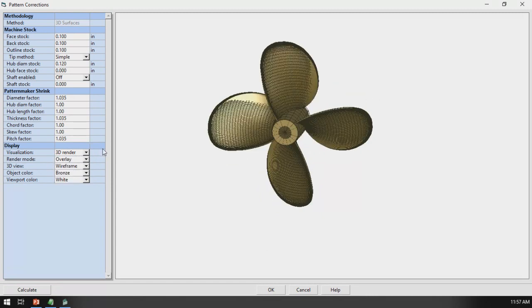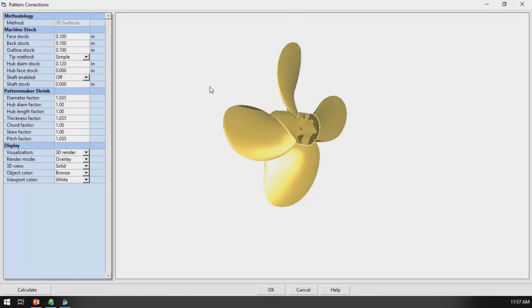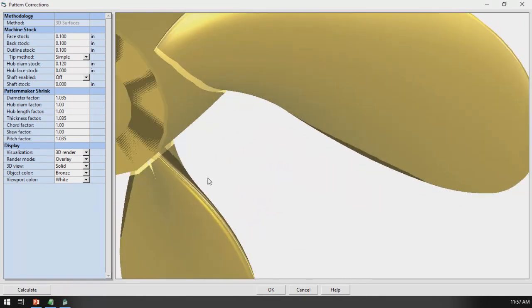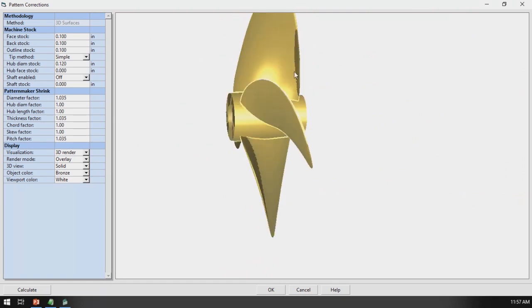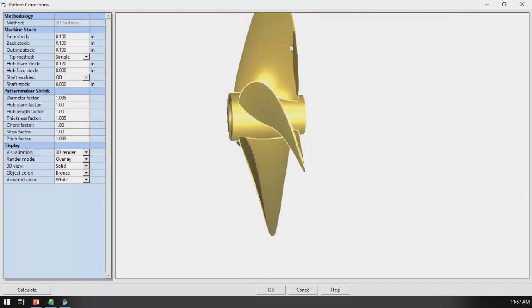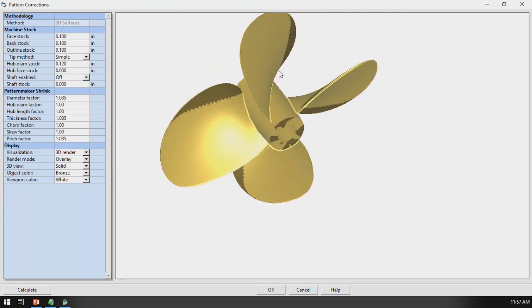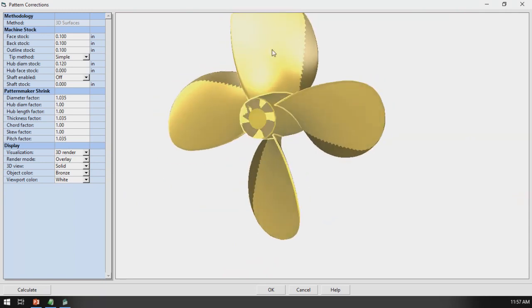All right. Hopefully that answers any questions about this pattern making utility and making compensation. This is just another way to visualize the same thing. Again, offset surfaces instead of a wireframe, it's yellow. But what this allows you to see is where your original design penetrates your pattern. And that's an indicator that you're going to have some rubbing in the mold as things contract. You may have some distortion. So this is a very useful utility, a very useful view.